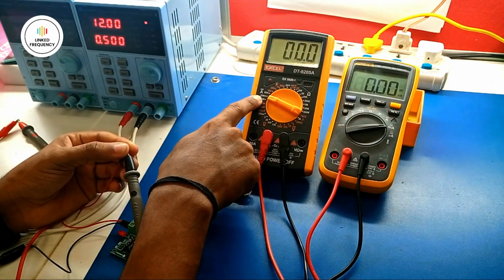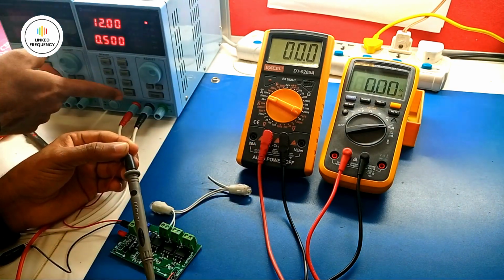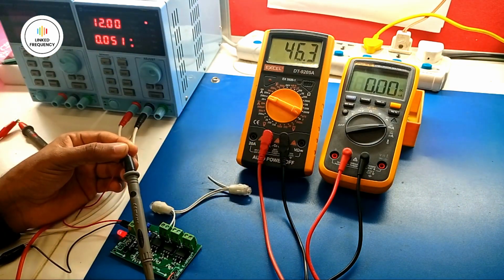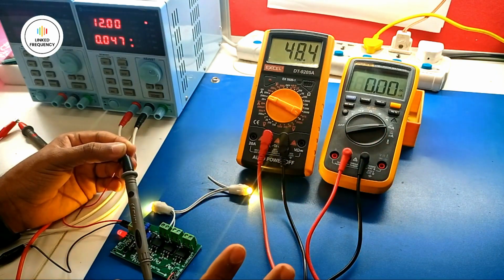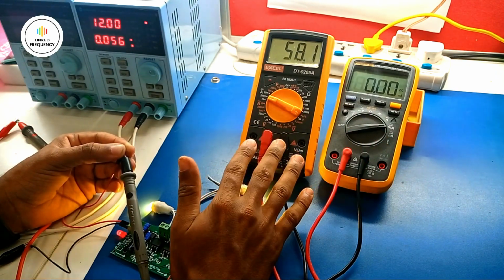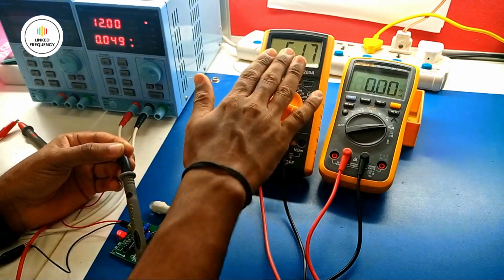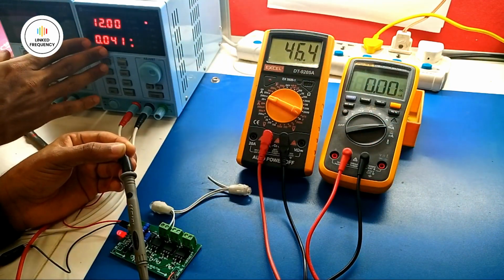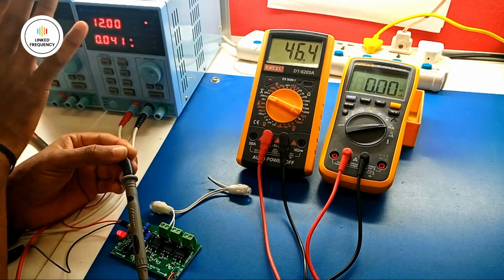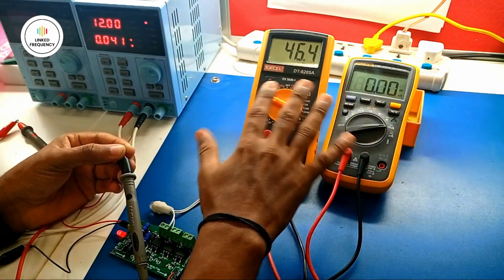So I'm going to set it to 200 milliamperes and then turn on the power supply. When I turn it on, you can see that 46.3 milliamperes and 61.7 milliamperes are shown to us, which means I believe the Fluke one is much better, because again this is a very low quality one, low precision, low accuracy, but still it is showing approximately near to this Fluke one. But this power supply has a completely different reading, so I just ignore the power supply. I consider both of them.